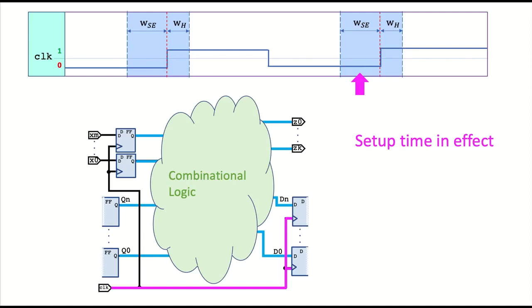Good designers who make flip-flops want to minimize these times because they determine how fast you can run your designs. So people who want high performance want flip-flops, or circuitry, that have very small setup and hold times.